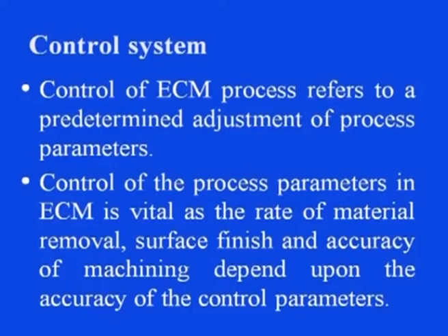Let us see the control system involved in ECM system. The control of ECM process refers to a predetermined adjustment of process parameters. Control of the process parameters in ECM is vital as the rate of material removal, surface finish and accuracy of machining depends upon the accuracy of the control parameters.